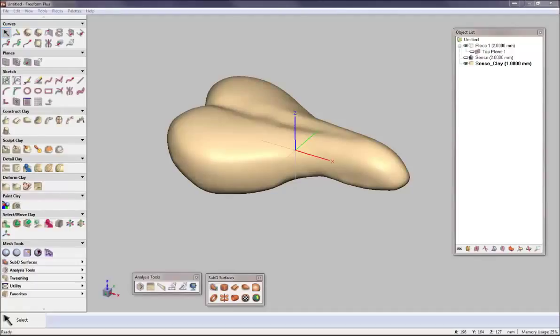Yeah, I'll go ahead and take that. Depending on the tool, it's using the surface normals. For example, with the hot wax tool, depending on what setting I have it on, whether it's add, remove, or smooth, it's using those directions to activate the tool when I click it.